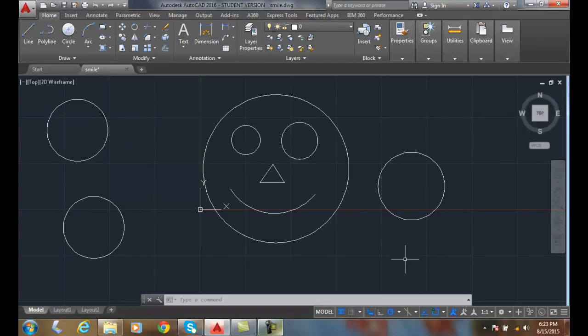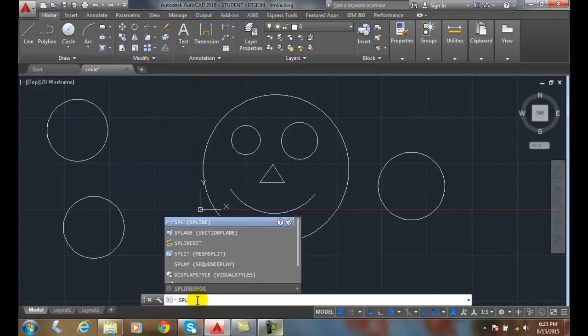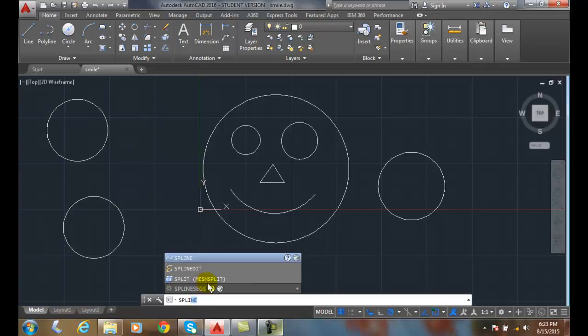Input search tools. We have some input search tools that we use with our AutoCAD commands and system variables, and they are things like Autocomplete and Autocorrect. So Autocomplete, if I'm typing in something like spline, it goes out and finds the spline command for me, and so it says, oh, okay, SPLI, and there's auto spline, so it auto fills it in.